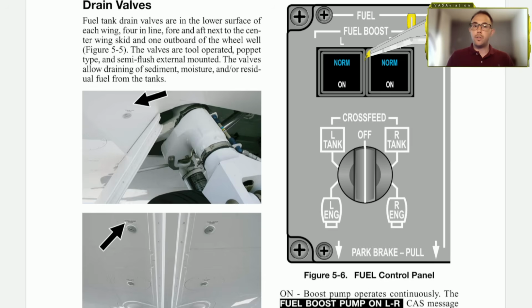This is something that we use very much on a real basis, and this is very interesting in the Cessna Citation, and it's that we have an APU. The APU is the auxiliary power unit that we have in the back, in the tail of the aircraft, and we use it on the ground for electrical supply. When we're waiting for passengers and we need electricity in the aircraft to start powering up the aircraft and start setting up the FMC for the flight and everything, and also for the air conditioning, we use the APU, and that APU in the Cessna Citation, we only burn fuel from the right tank.